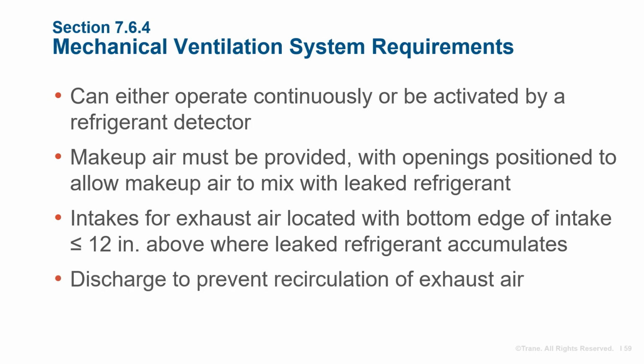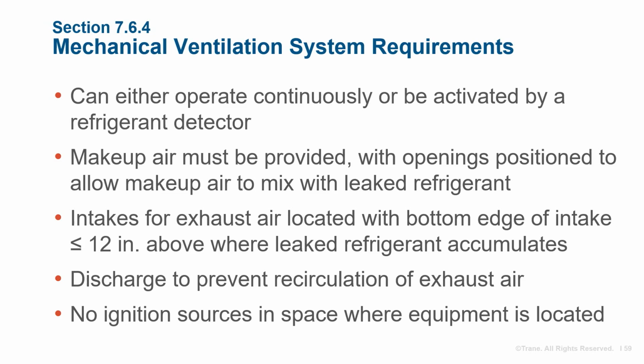Discharge of this exhausted air must be located to prevent recirculation back into the space. And no open flames or hot surfaces can be installed in the space where the equipment is located. In addition, the standard requires this ventilation system to be verified by a monthly self-test to confirm operation.